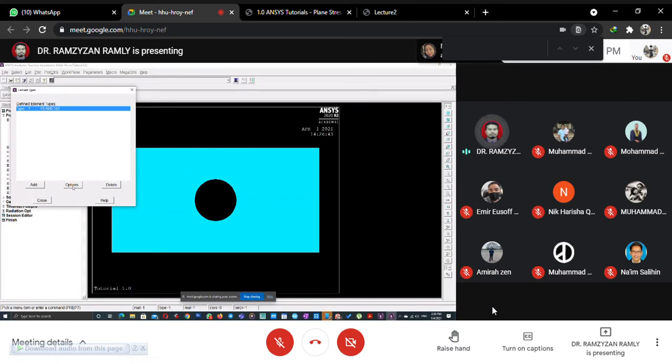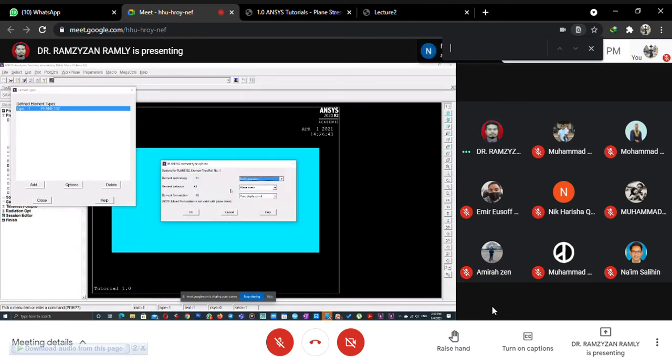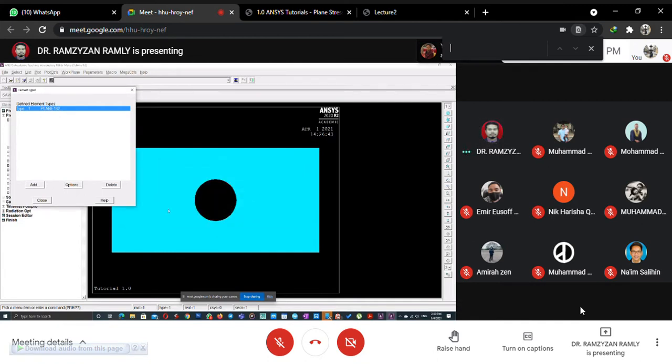Okay, and then we pick options. Okay, the option according to the tutorial. What I want to choose is that under K3, plane stress with thickness. Okay, K3, we choose plane stress with thickness. Okay. And then we can close.